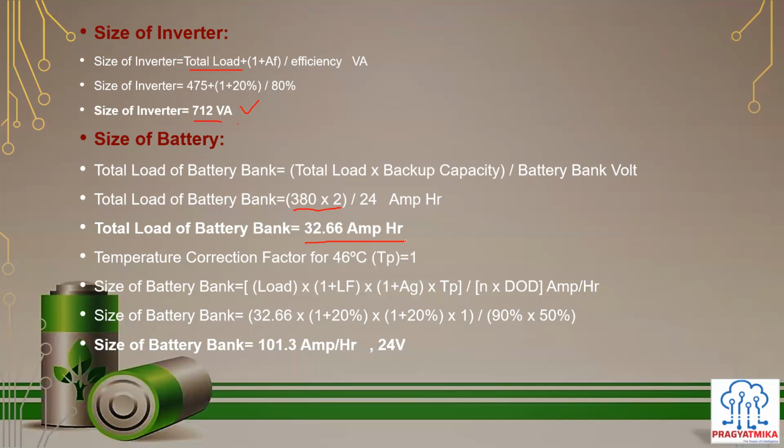There is a change in the pattern of the discharge current. I think we have seen the correlation earlier: if the temperature is quite high or quite low, there is a change in the pattern of the discharge, and if the temperature is near room temperature level, the exact amount of discharge you are expecting will happen, and you will be able to use the maximum of the capacity.